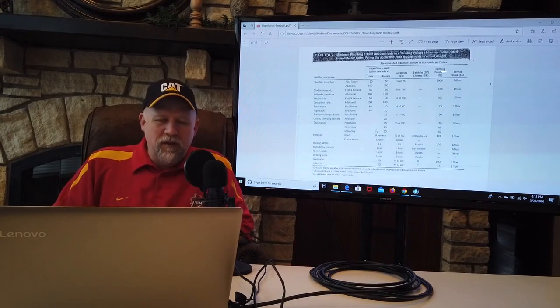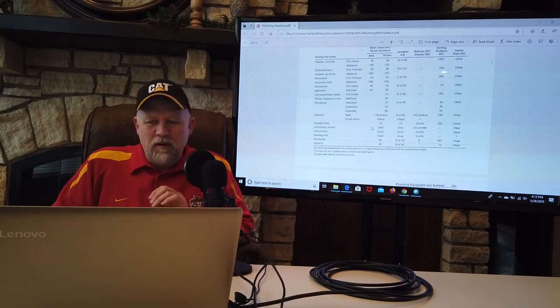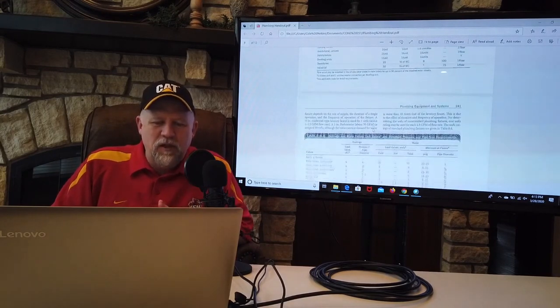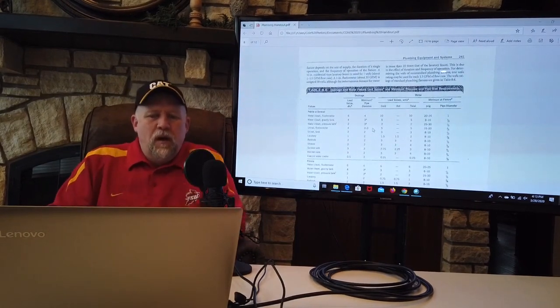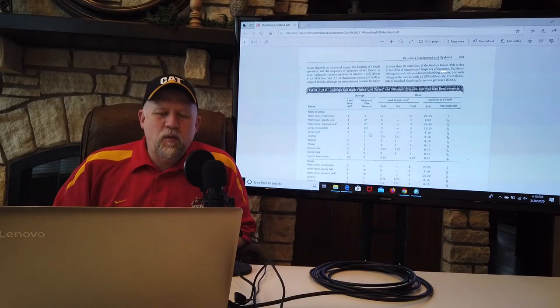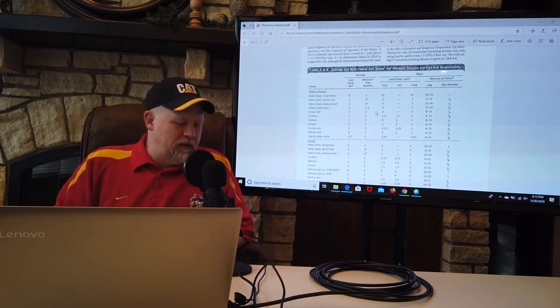All right, so do the calculation, get the total number of water closets for men, total number of water closets for women, and then let's go to the next page. All right, we're going to need to calculate drainage fixture units and water fixture units.